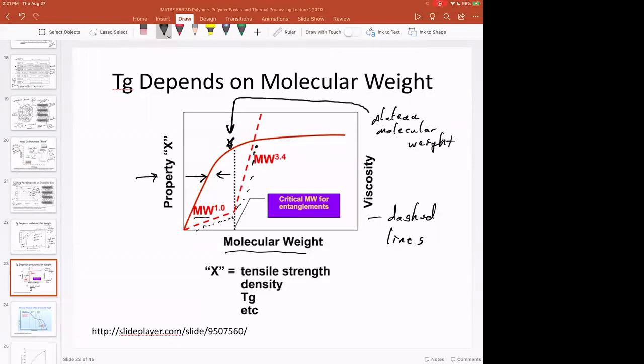So there's only one plateau molecular weight, and that's it. So below the plateau molecular weight, if you double the size of the oligomer or you double the molecular weight of the oligomer, your viscosity is going to go up by a factor of 2. That's fine. You make the molecule twice as big, the viscosity is twice as high. You make the molecule 4 times as big, the viscosity is 4 times as big. We can sort of get that.